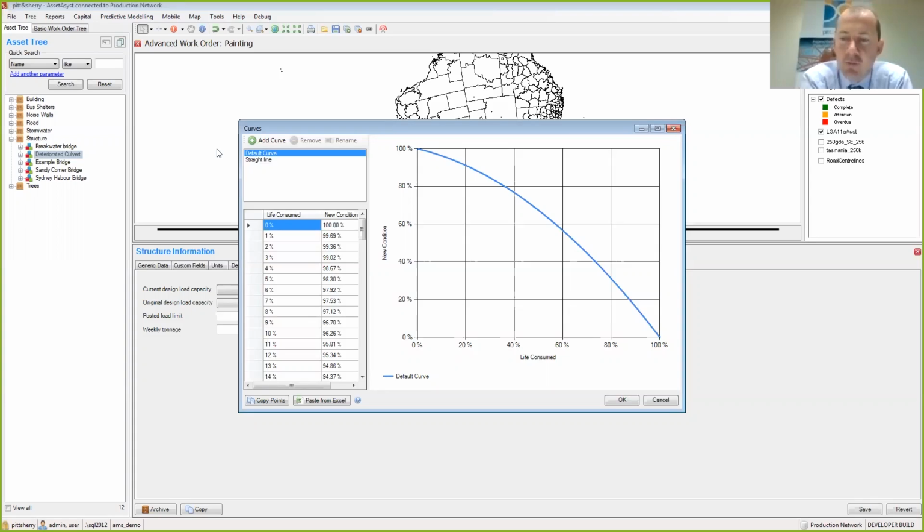And by that I mean applying testing to structures which has a direct relationship to how long they're going to last and is scientifically proven, rather than observing deterioration and using that as an indicator of what's going on. Because often by the time you observe something, it can be too late, and using just your eyes to understand the depth of chlorides is not the right way if that's the mechanism that's leading to deterioration of your concrete, and therefore corrosion of the steel reinforcement. By the time you observe it, it'll be too late.